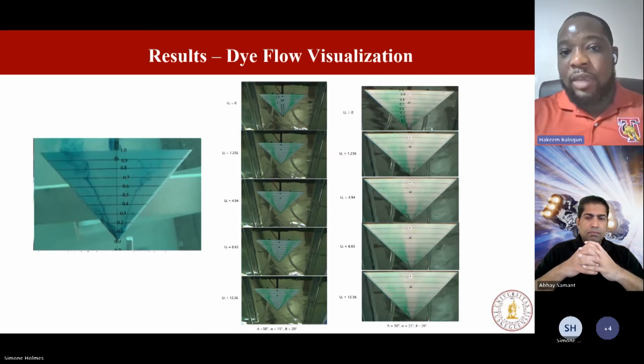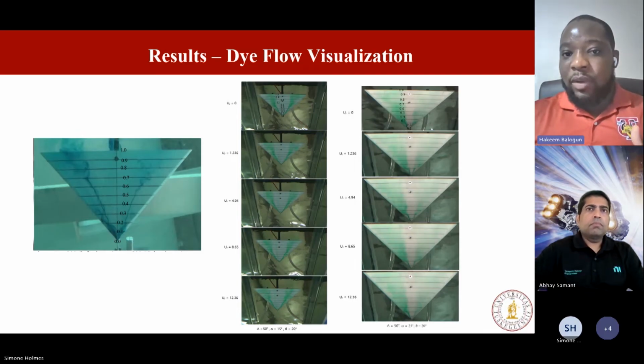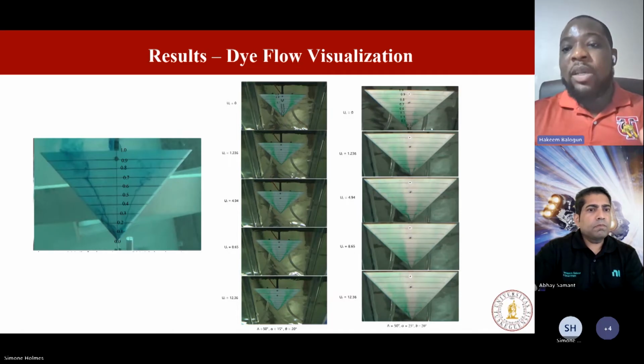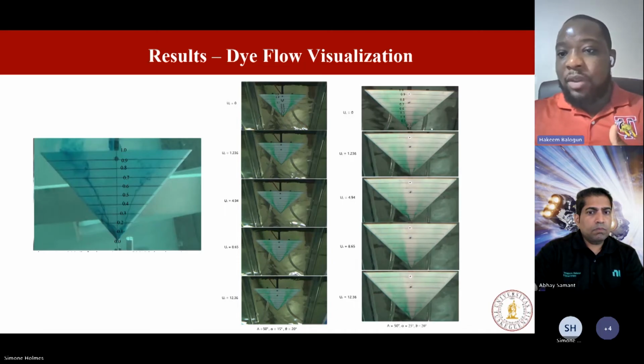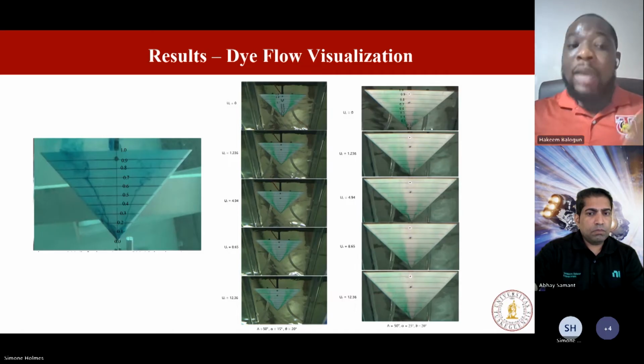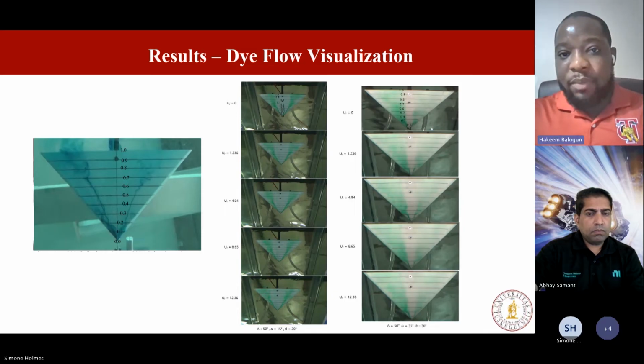So for the 15-degree case, we didn't get a noticeable change in the vortex breakdown location, but we did notice that the vortices were being influenced by the jets. But for the 25-degree case, we saw more evidence of the vortex breakdown location moving further down the chord. And we also noticed the rate of rotation about the vortex axes of the broken down structure increasing as well. Next slide.